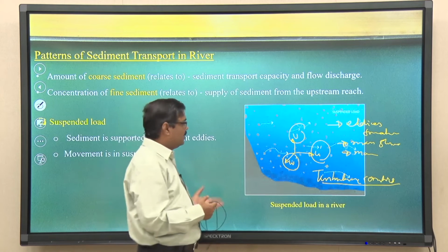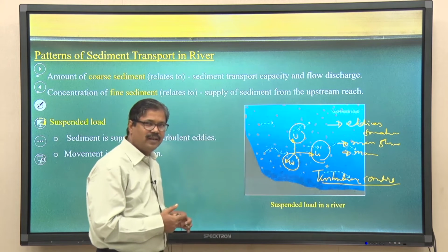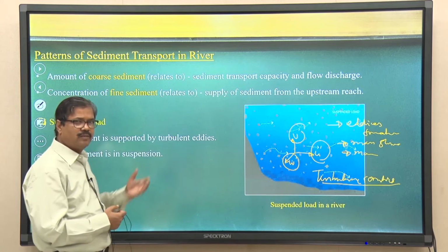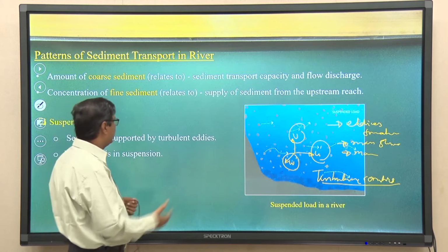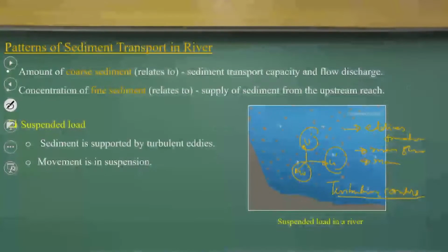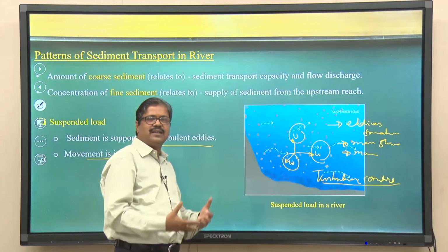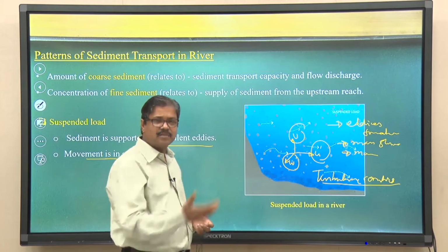But as this course is meant from the river engineering point of view, we will not go into much detail on turbulence characteristics. Overall, the sediment is supported by these turbulence eddies and movement in a suspension stage. As the turbulence intensity decreases, the suspended particles again start depositing.